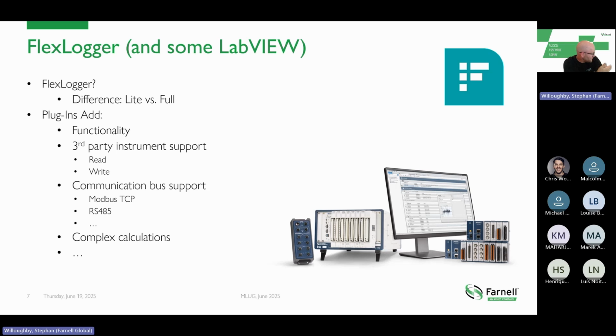So my plan was to connect an arbitrary waveform generator, so you can write third-party instrument support using SCPI, or you could communicate to an existing controller using Modbus TCP, or a sensor using RS-485, or do PID control or other complex calculations that aren't included in the existing calculations, like averages, min, max, that kind of thing. So anything outside of that, this is how you'd add it into FlexLogger.